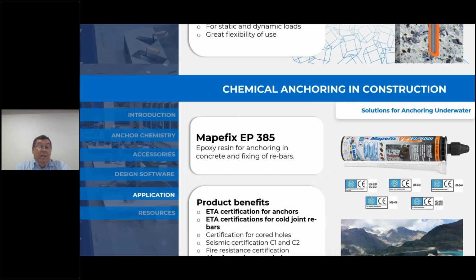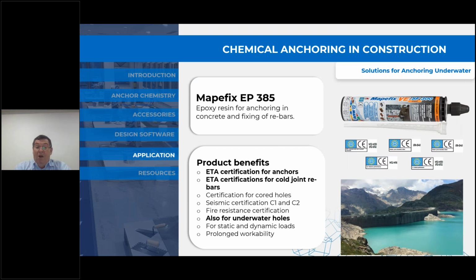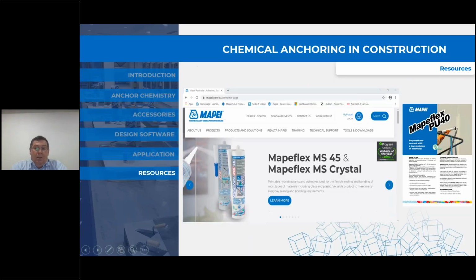From there, we move to the Mapei Fix EP385, and it is 100% solids epoxy. Sorry, that is the wrong drawing there. And it has the most certifications. So this EP385, the 100% solids epoxy, is the top of the range as far as anchors go. So it can be used across the board in all applications.